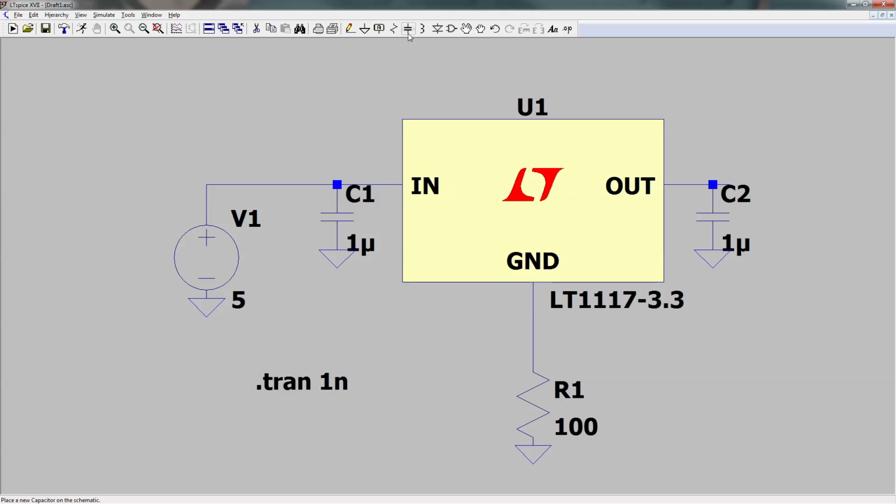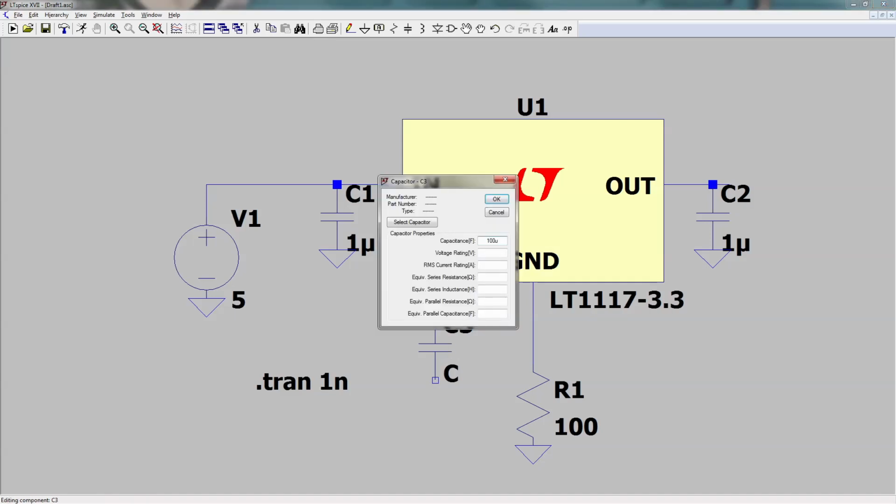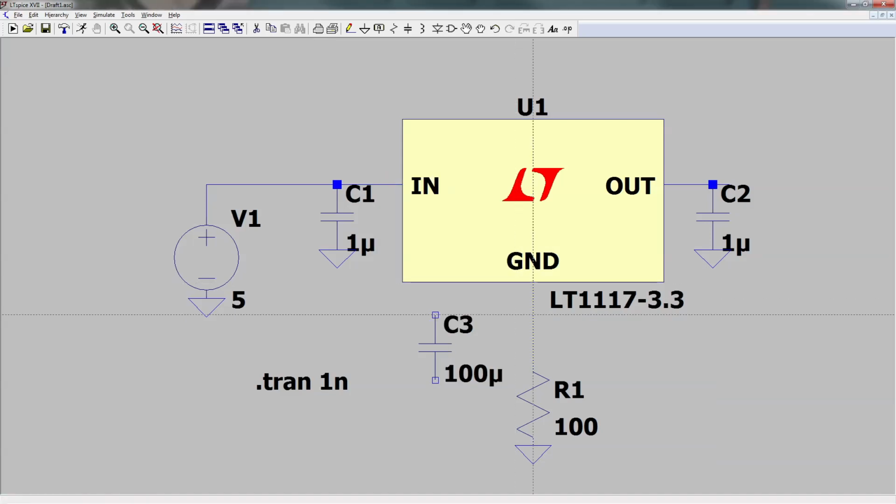Now, no matter how you do this mode, if you use the diode or the resistor, but okay, especially in the resistor version, it is a good idea to also have a capacitor here, and maybe a quite big one, maybe 100 microfarads, and stabilize this node to the ground. Yeah, so that with some transient stuff here, this node does not bounce around.